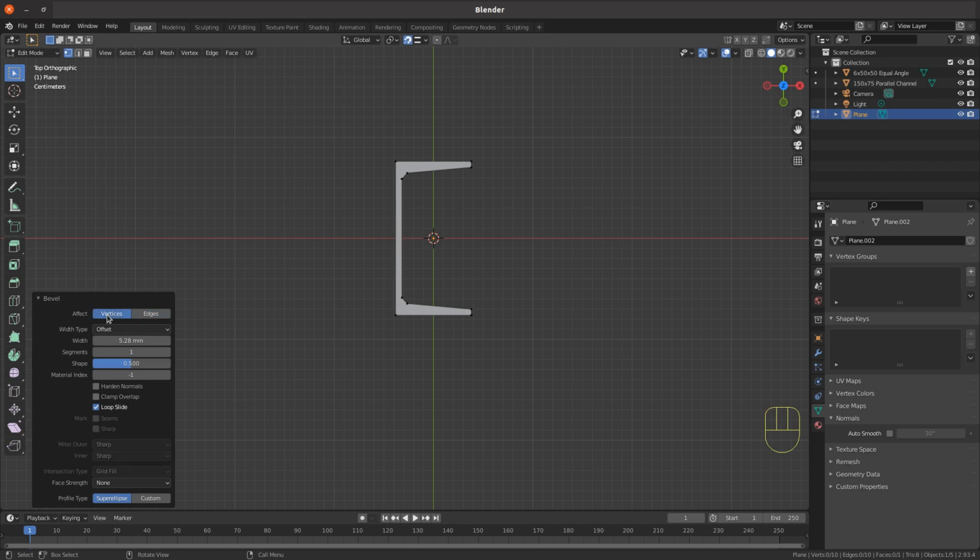And we're vertex beveling, and the bevel needs to be 12.2 millimeters in the width panel, so 12.2 in there, and again we'll segment it 7 times, so you've got 8 segments, 7 new vertices on the inner bevel.